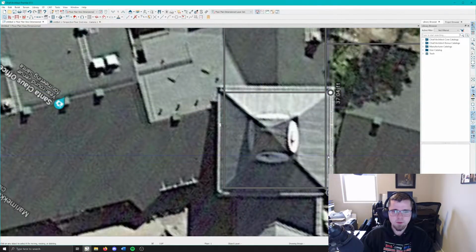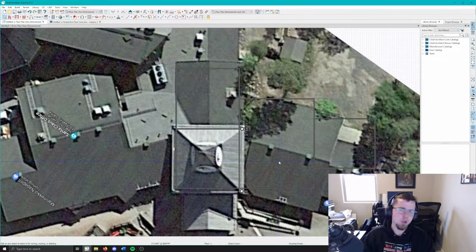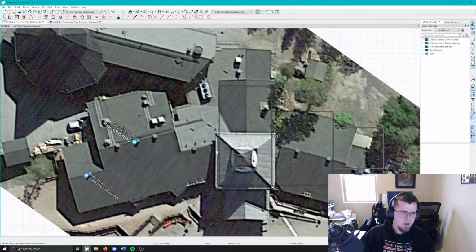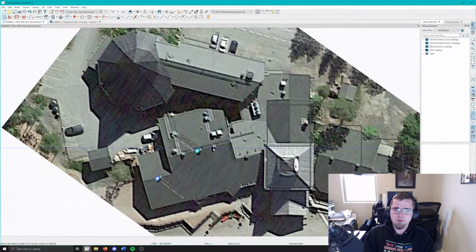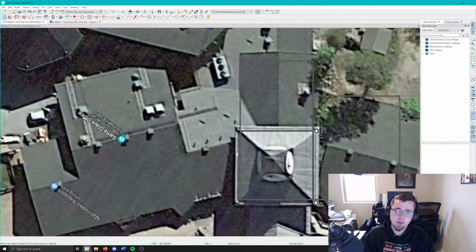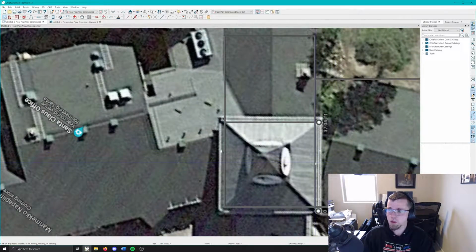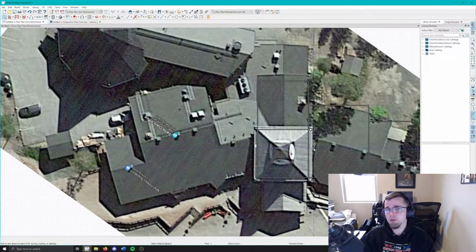Something that I do run into a lot when people bring me drawings, and they acknowledge it, it's not a problem, we fix it: as they draw out layouts for their home, if we are working with very limited space, generally they don't account for the thickness of walls. These walls right here, I have drawn as 6 inches. Realistically, these could be a foot thick. And if they're that thick and there's 2 or 3 in a row, you just lost 2 to 3 feet on the size of your home.